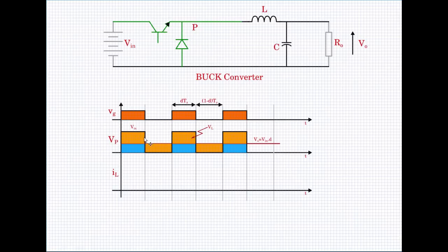So this way, the pole voltage here has so much information in it. It gives you the average of the output. It gives you the voltage across the inductor and the volt-second balance that is happening. And with this, we can rate these two components.